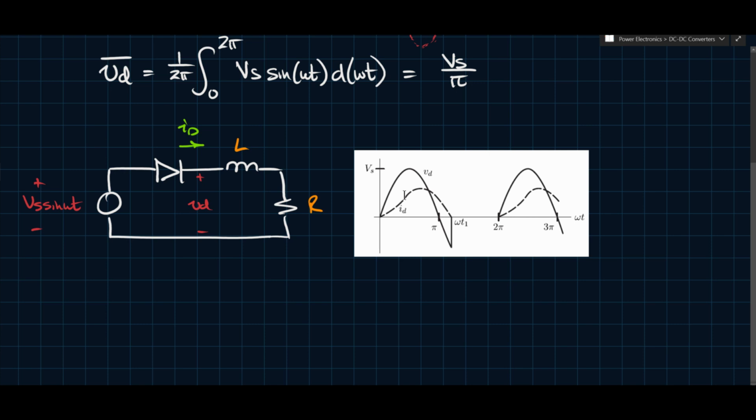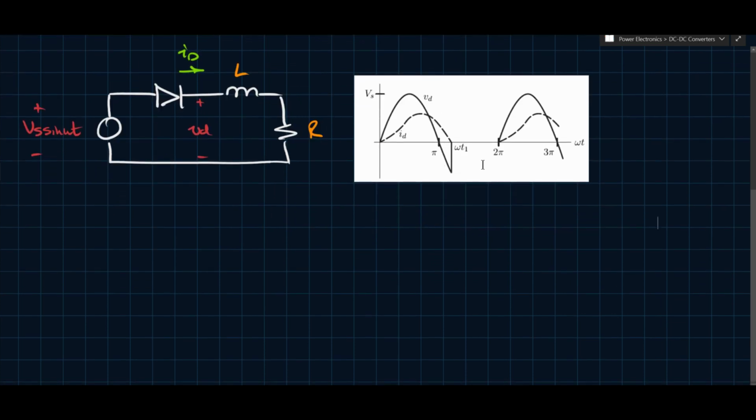But it would also introduce a phase shift between the voltage and the current, as inductors do, because if you want to think about it in terms of power factor, now the power factor is no longer 1, right? Or you've added a reactive component here. So the overall thing shifts according to whatever the combination of these two is in the complex domain, right? So what are the two main differences here? There are two key differences, and if they aren't obvious to you, we can discuss them.